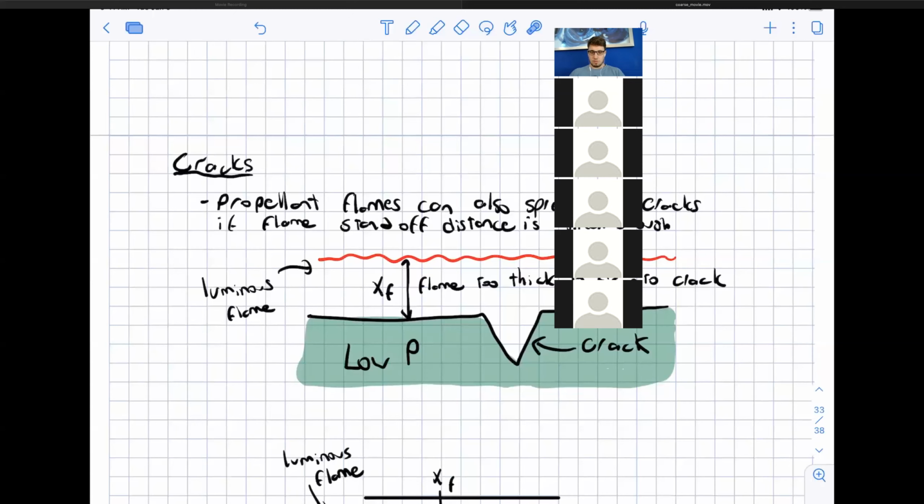So it's a big problem if you have a rocket system that's sitting around for a long time, and you have the unfortunate event where you need to push the go baby go button and basically light it up. You need to understand how these cracks, which can form in the propellant surface, can affect how it burns. And if the pressure for your rocket system is low, they're not going to matter very much. These cracks are very thin. This is a very exaggerated view of them.